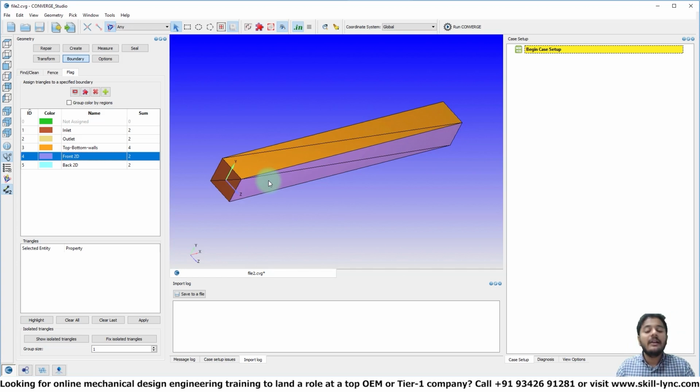But why 2D? Well, what we want to do is run a 2-dimensional simulation. Now I understand that the geometry is 3D. We are going to pretend that this geometry along the z-axis has infinite length, meaning you don't have to simulate the flow entirely on the 3D geometry. You can just take any 2D slice and the flow pattern is going to repeat itself again and again, right?